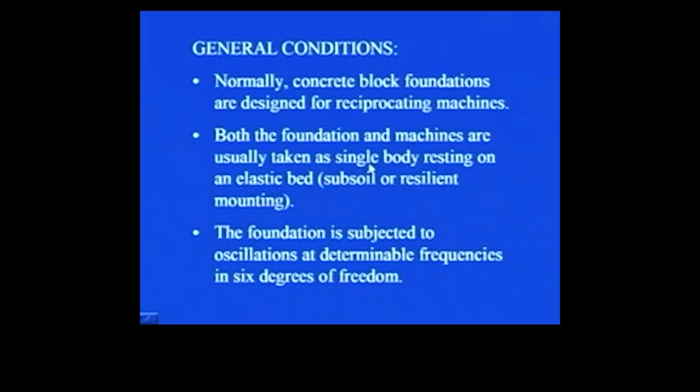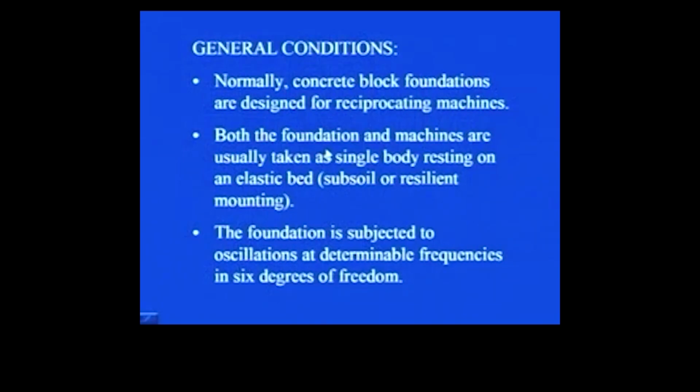So what happens is, first you cast the foundation and then on top of that you mount the machine, but they do not work as two different units, they work as one integral unit. So that is one of the general conditions, that both the foundation and machine are taken as one single unit when the machine is operating.